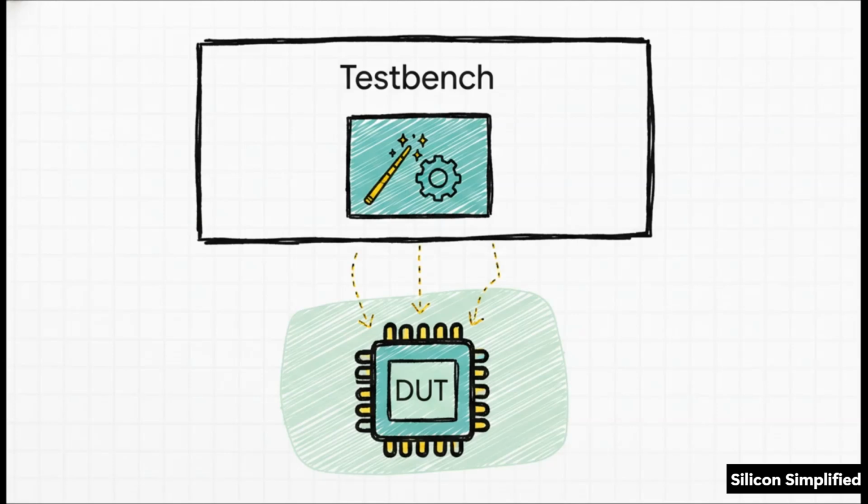What makes UVM just incredibly powerful is the UVM test component. This thing is dynamically created at runtime using a factory registration process. So what does that mean for us? It means you literally only have to compile your test bench once, just once. But you can run countless different tests because the UVM test dynamically instantiates the top-level environment, configures the whole shebang, and then applies specific stimulus straight down to the DUT.